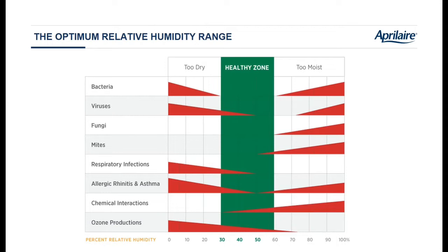In fact, we might cause some things to be more of an issue. So save yourself some headaches. Save an awkward conversation with tech support. Keep the relative humidity below 60%, so set the dehumidifier to maybe 55%. Keep it below 50%, so it's maybe 45% or so. Those are the numbers you want to shoot for.